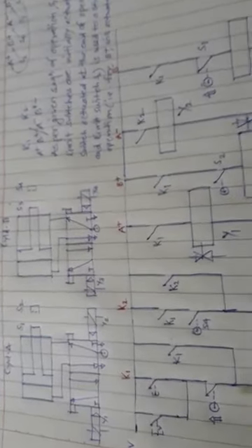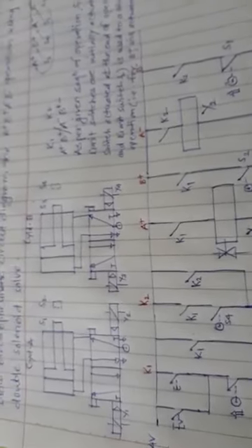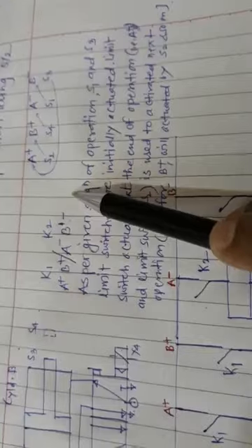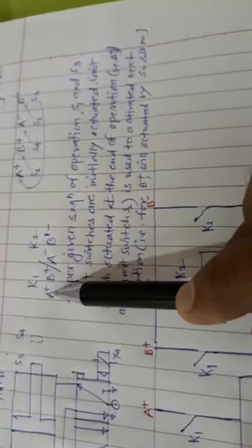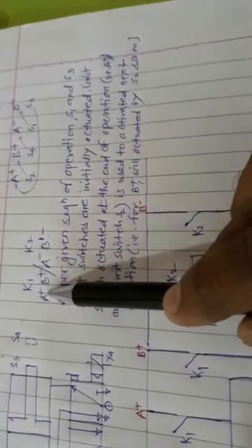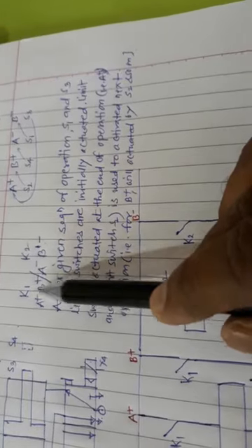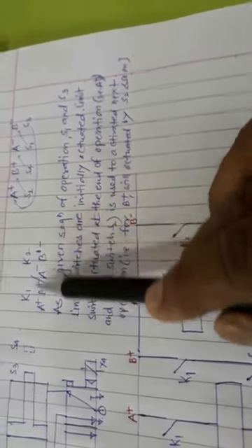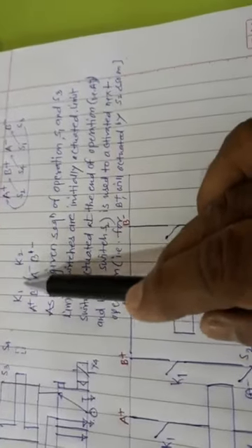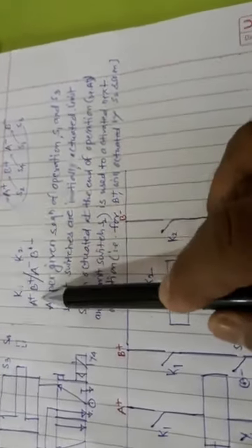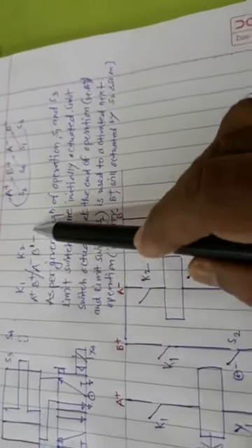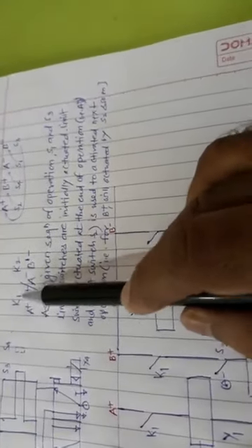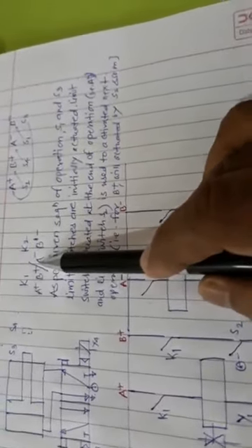So here we can see which operation will be activated by the end of which limit switch. Now we are dividing this sequence of operation into two groups, K1 and K2. Here we are taking care of the rules for forming the groups. No two operations of a single cylinder belong to one group, so we divide into the minimum number of groups. We can divide into 4, but then we have to use relays K1, K2, K3, K4 for the 4 operations. Besides using 4 relays, it is better to use the 2 relays K1 and K2. So A plus, B plus belong to the K1 group, A minus and B minus belong to the K2 group.